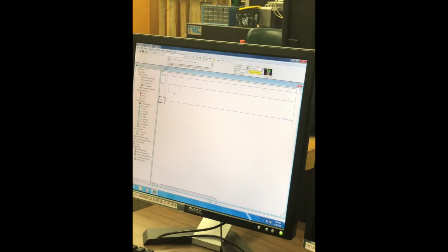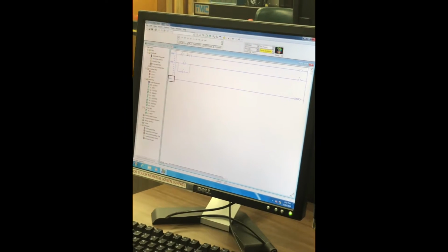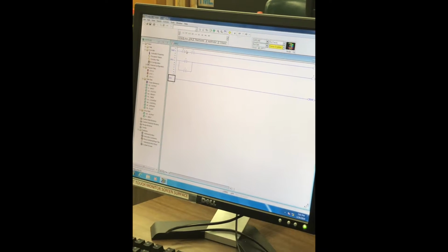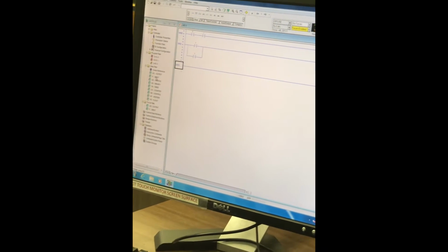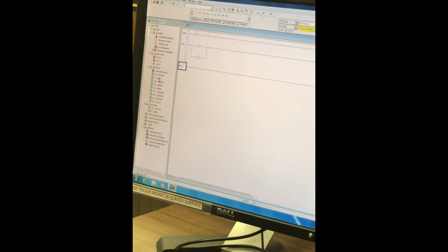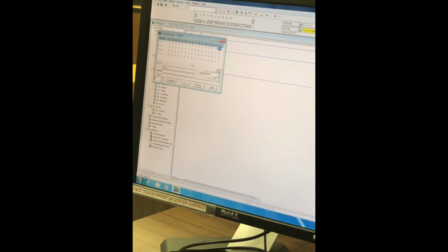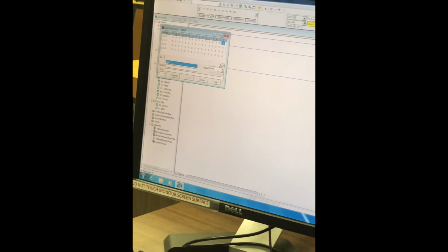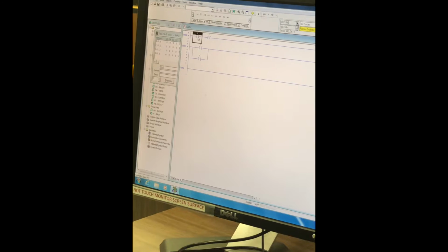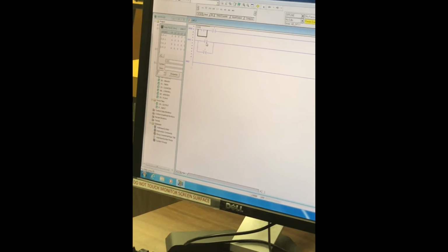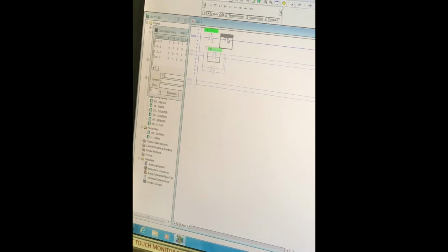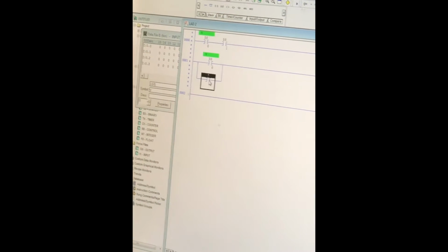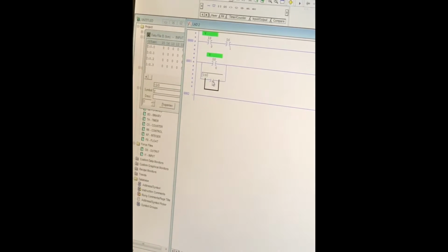Then essentially we're going to change the addresses now. For this, we get the address right here. For example, the input port has 1 input card and 1 output card. So you double click on input, and we select the first address, which is I0/0. You copy it, Ctrl+C on your keyboard, and double click here and paste the address. Now we can do the same thing here. This one is just going to be 1, so I can just put 0 and then put 1 at the back. Likewise, this one is going to be I0/1.